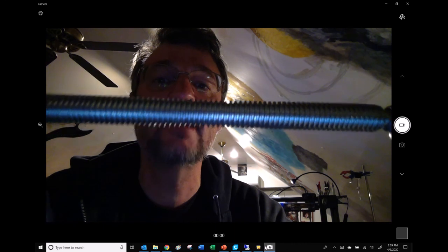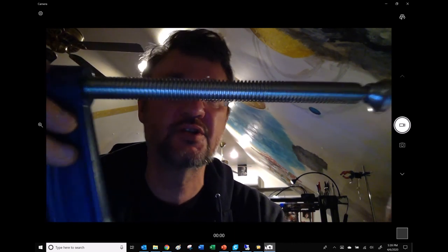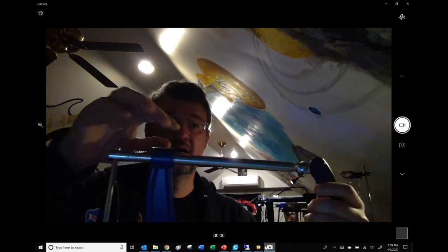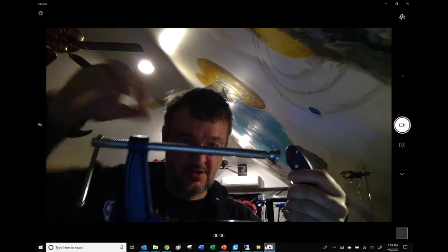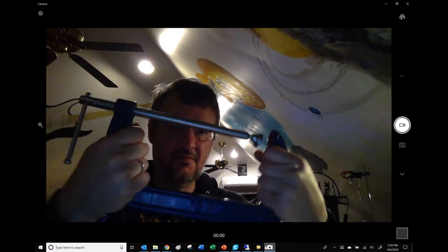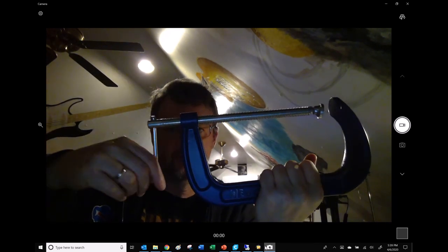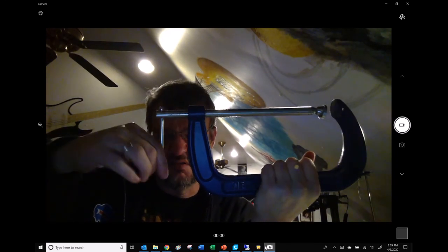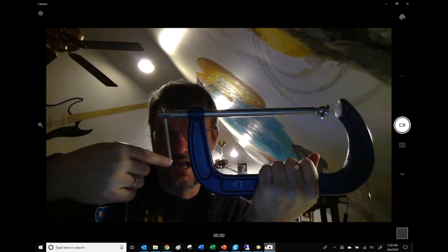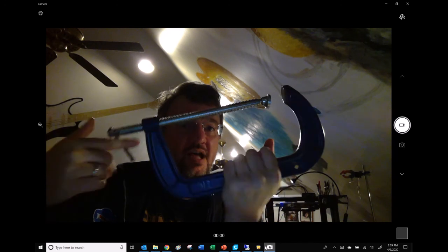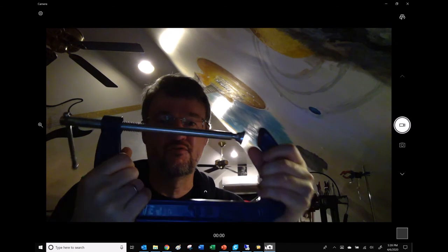And when I have people do an assignment with this, we try to figure out what's going to fail first. Is it going to be these bolt threads, and they're probably going to fail right in here? Is it going to be from the bending of this, or maybe this little handle? Probably this little handle is going to bend. But if you were to put a force right on the end of this thing and torque something down, which would go first?